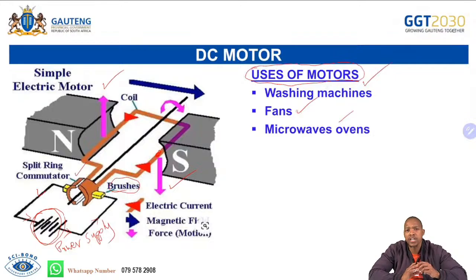So we have generators, we have motors. Generators work on the principle of electromagnetic induction. Motors, the motor effect. With generators, we always determine the direction of current. With motors, we always determine the direction of motion. What do we use to do that? In generators, we use the right hand FBI rule. In motors, we use the left hand FBI rule, where the F is force for both, the B is the direction of the magnetic field, and the I is the current.